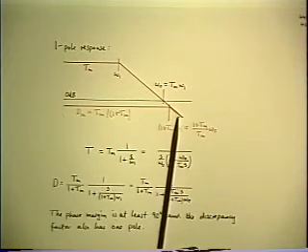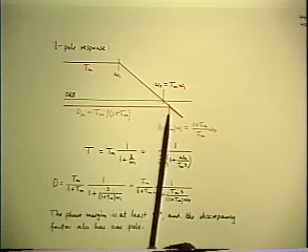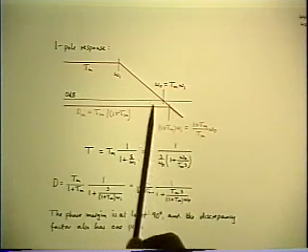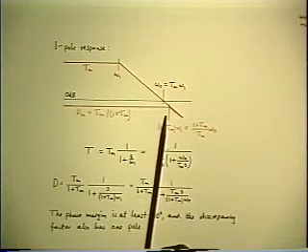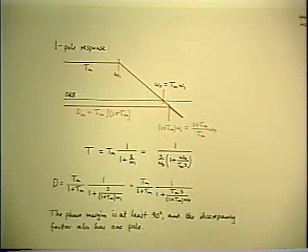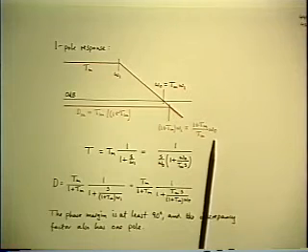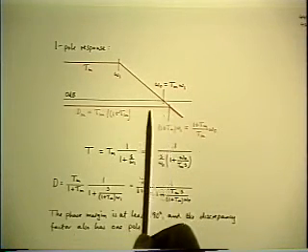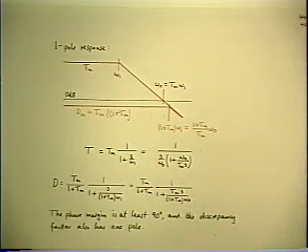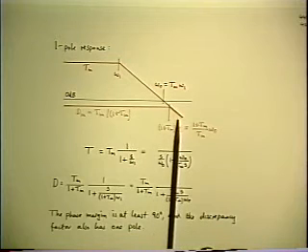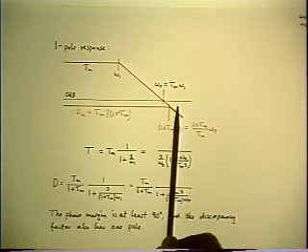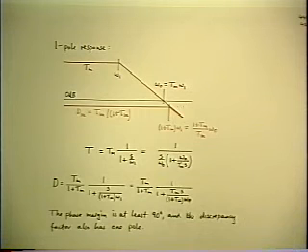So the closed loop gain that you get for this case is a flat value and a single pole, which of course actually has a 3 dB smooth corner. Now that's the ideal case. That's the best possible shape for D that you can ever get, given that it's going to roll off somewhere. So flat up to a certain frequency and then a smooth 3 dB corner is the best you can do. In other words, it's the most graceful roll-off of the closed loop gain you can get, where it begins to deviate from the G infinity. What's the phase margin in this case?